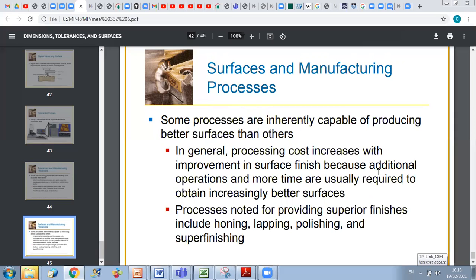I will just give a brief explanation for each of these types. First we start with the honing process. Honing uses a special tool called a honing stone in order to achieve a precision surface. The hone is composed of abrasive grains that are bound together with an adhesive material. In general, honing grains are irregularly shaped, and the smaller the grain size, the smoother the surface of the